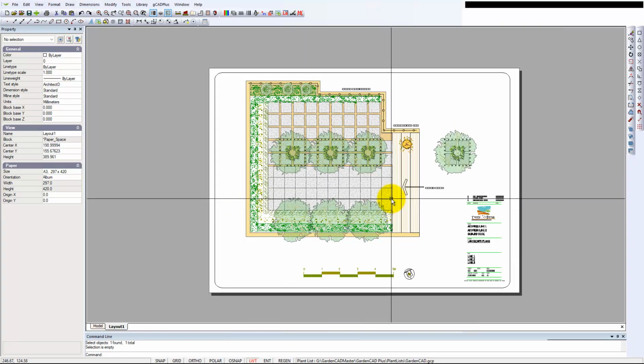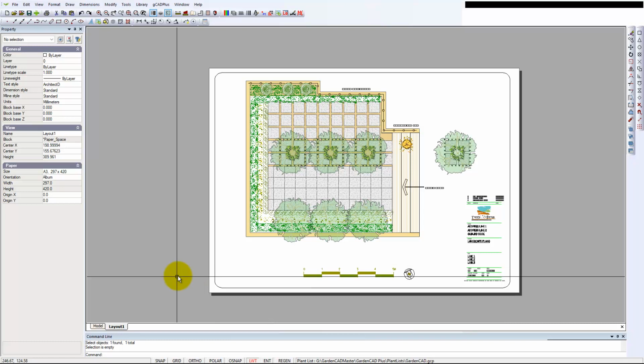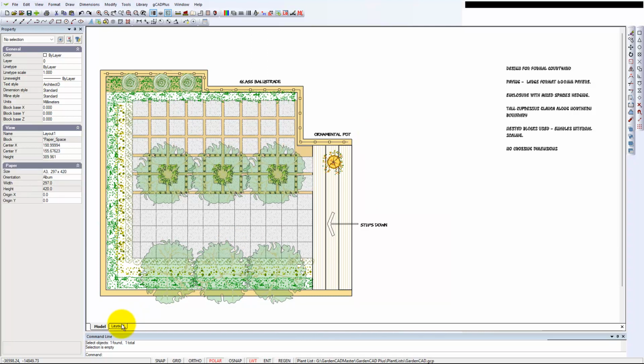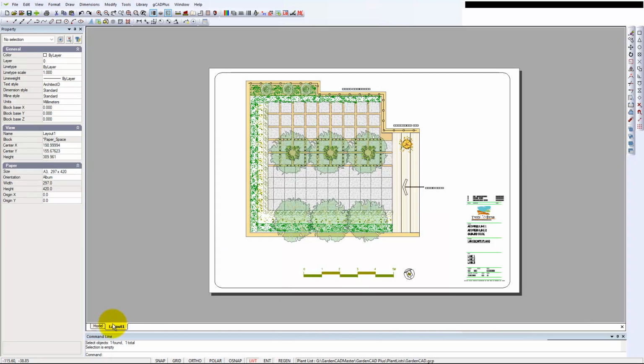So if I wanted to add features, we could go back here and take that one out and come back in here into layout. Just say we wanted to add notes, you could easily rename that layout. We could easily add a new viewport, and I normally like to control these by putting in a box about the size that I want.